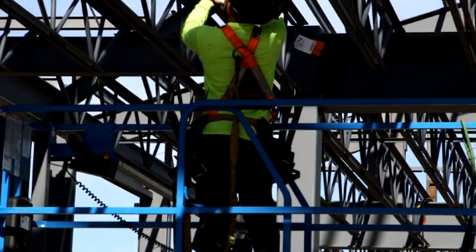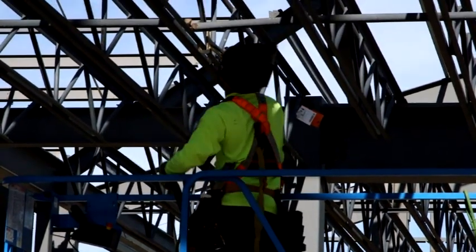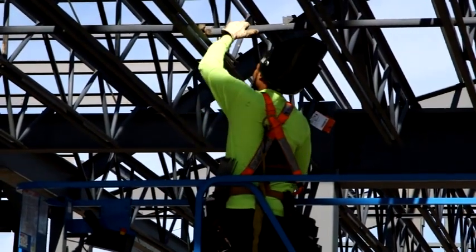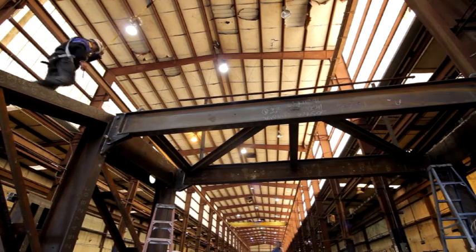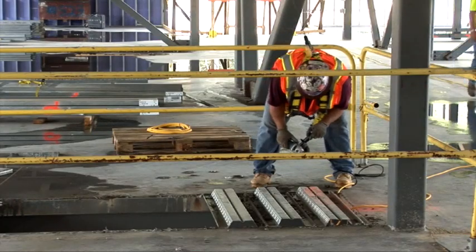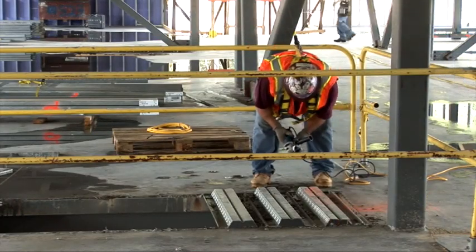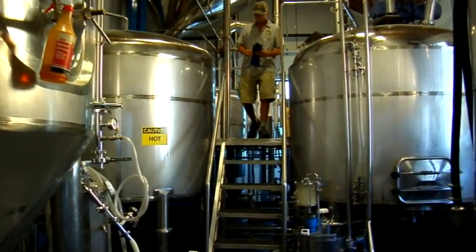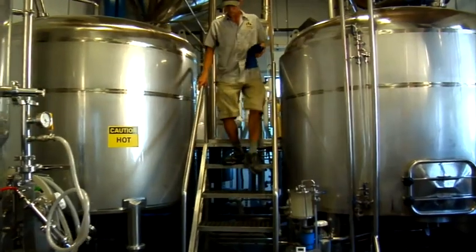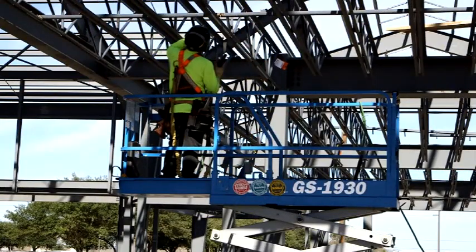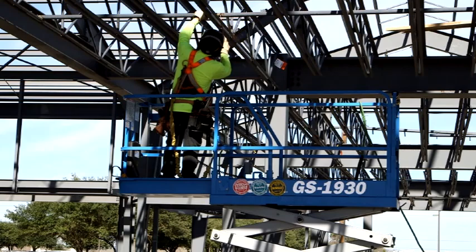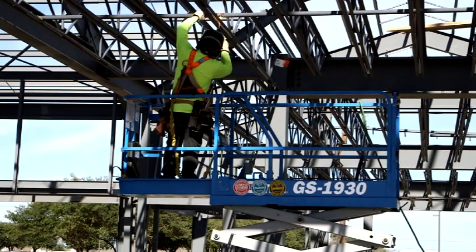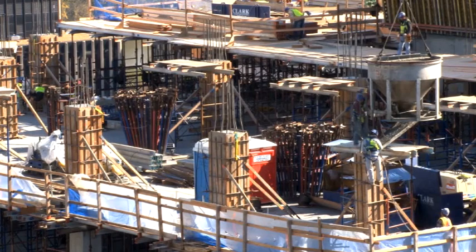Fall protection must be provided for each employee on a walking, working surface with an unprotected side or edge at the height required by the OSHA standard applicable to their workplace. In general industry, the elevated height level is 4 feet or more above a lower level. In the construction industry, OSHA mandates employers to protect employees from fall hazards and falling objects whenever the employee is 6 feet or more above a lower level.